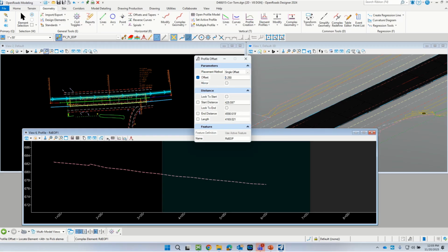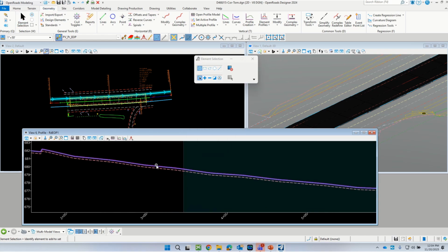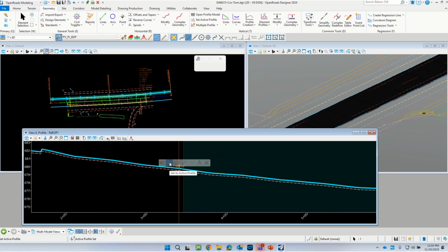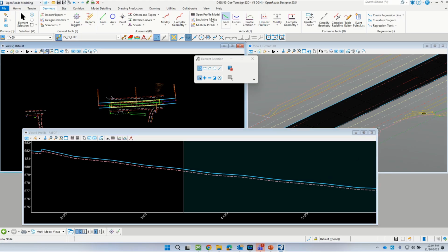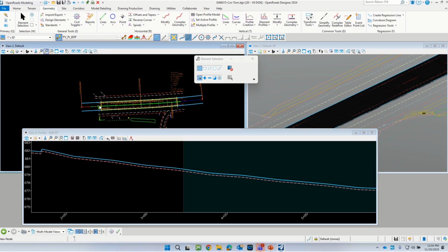and then whatever that overlay thickness is going to be, I don't know what it's going to be. Let me just set it. It's probably not quite that much. We'll just set it at 0.25 just to have something. And so then let's go ahead and store a proposed profile. And then now instead, I'm going to make that the active profile. And I would do the same for both, but let's take a quick look at that cross section again.